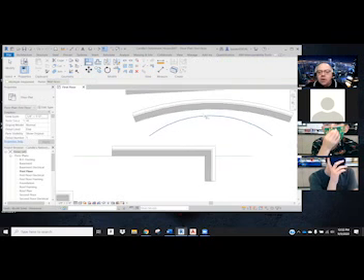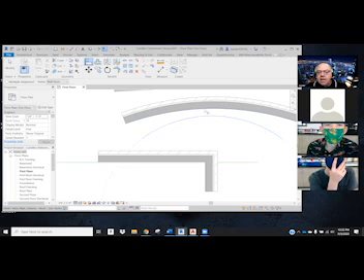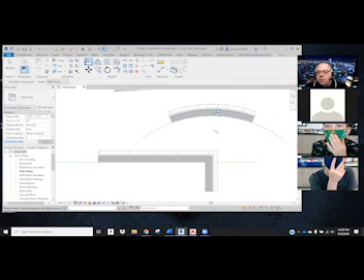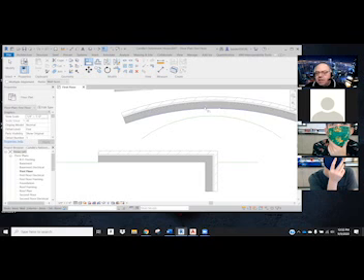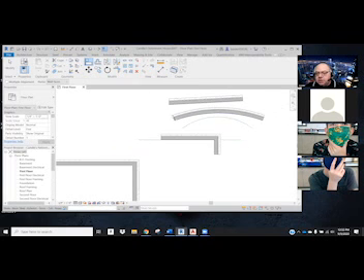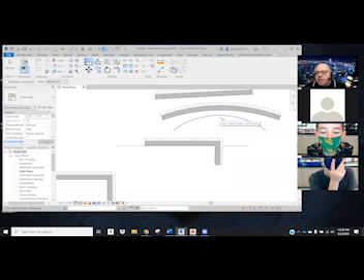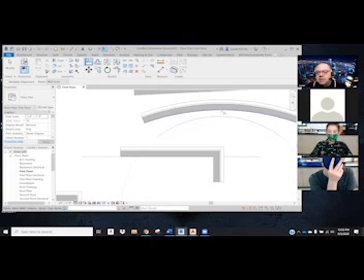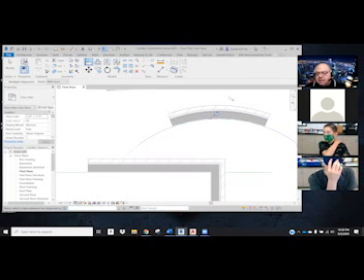The aligned wall, when I do a line, now I can bend that wall. Okay, so I'm going to do that again for you one more time. This radius is not what I want. So you want to draw it almost to what you want. Then when I do the align, I pick my AutoCAD arc or circle or whatever you're using, and then the edge of the wall that I want to bend, and it's going to pull it into that radius.